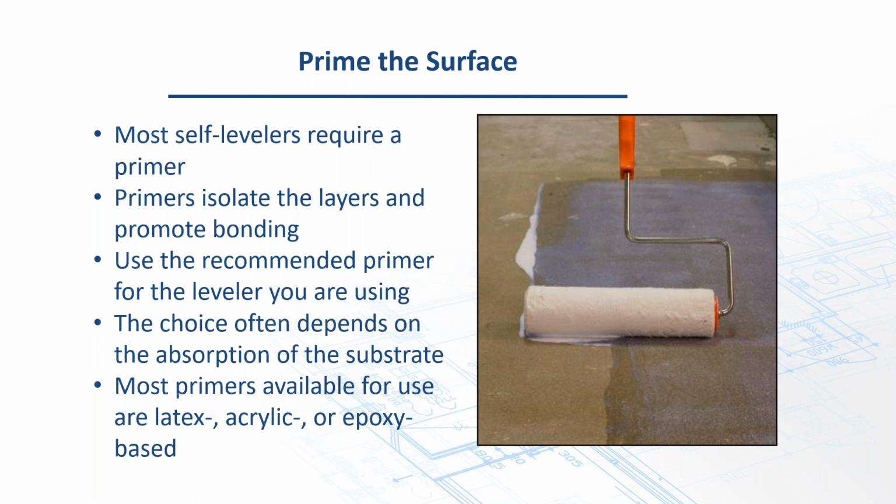So the choice quite often on the type of primer depends on the absorption of the substrate and what it is you're actually trying to achieve. Like, there are acrylic-based ones or latex-based ones. Some are diluted, some are not. There are epoxy-based ones. So again, it just depends on your project, the substrate, what you're trying to achieve. Take a look at the primers and selection charts for that matter.